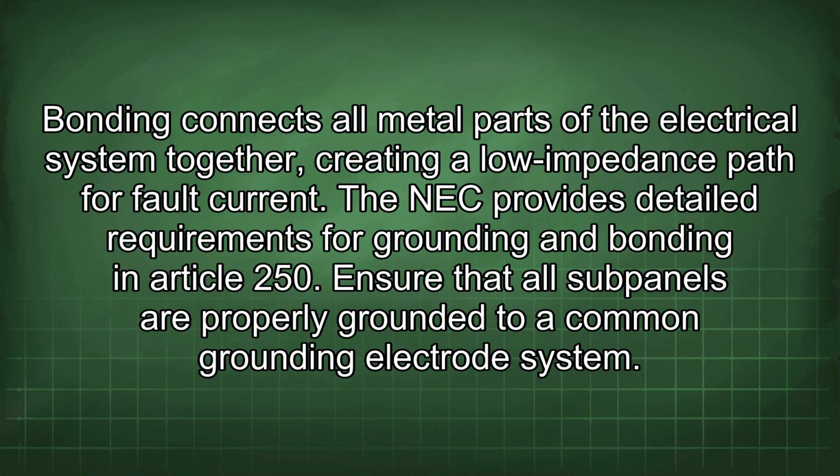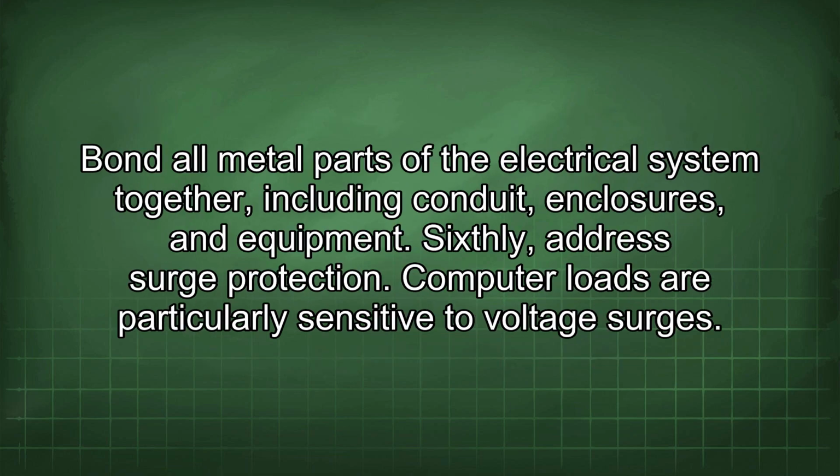Ensure that all subpanels are properly grounded to a common grounding electrode system. Bond all metal parts of the electrical system together, including conduit, enclosures, and equipment.